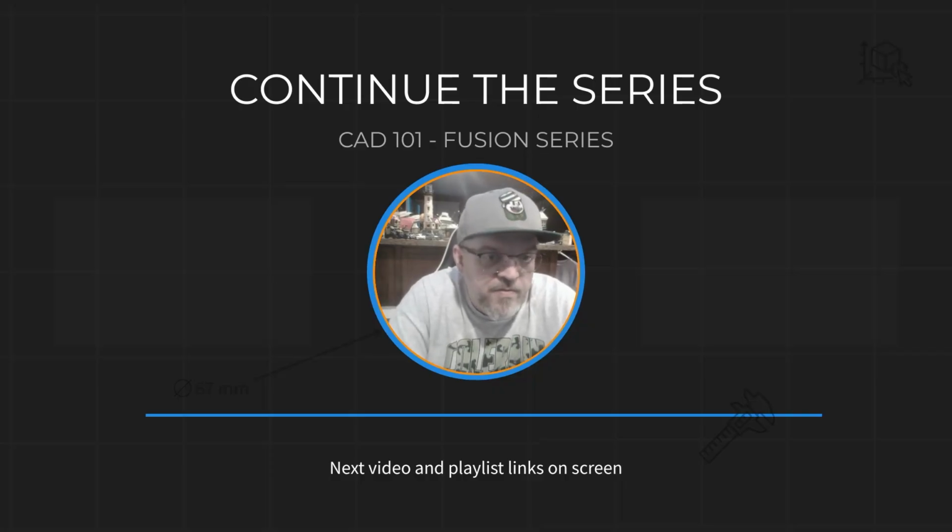Now we have the body tubes and the tail fin modeled separately. In the next video, we step up in complexity and we build the nose cone using arcs, lines, and the Revolve tool. Make sure your tail fin sketch is fully constrained before moving on. Clean geometry now is going to save problems later on when we get to assembling.